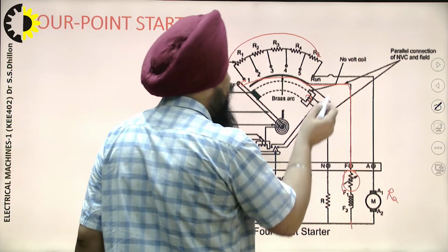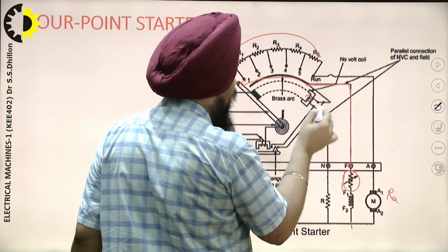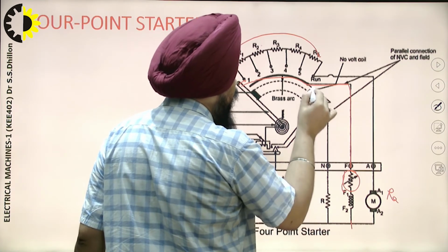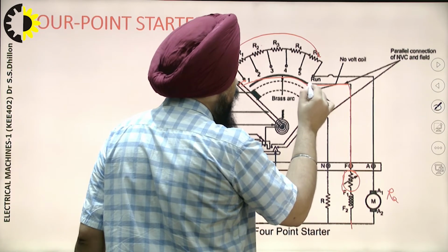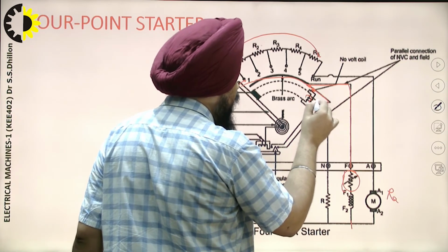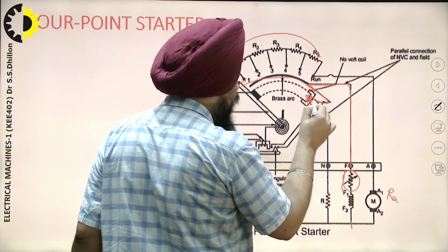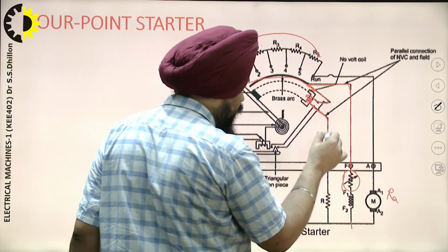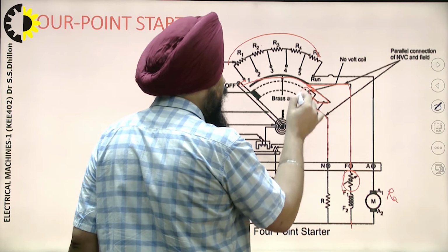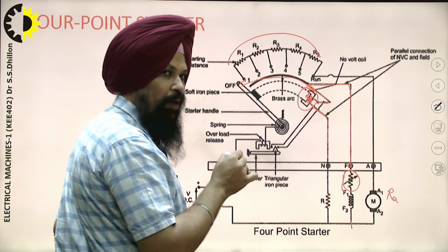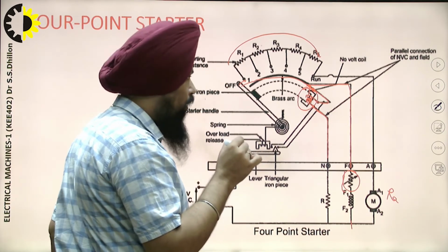But parallel to that, we have connected another coil. From here we have taken another terminal, a separate terminal for the electromagnet coil, or no voltage release coil.